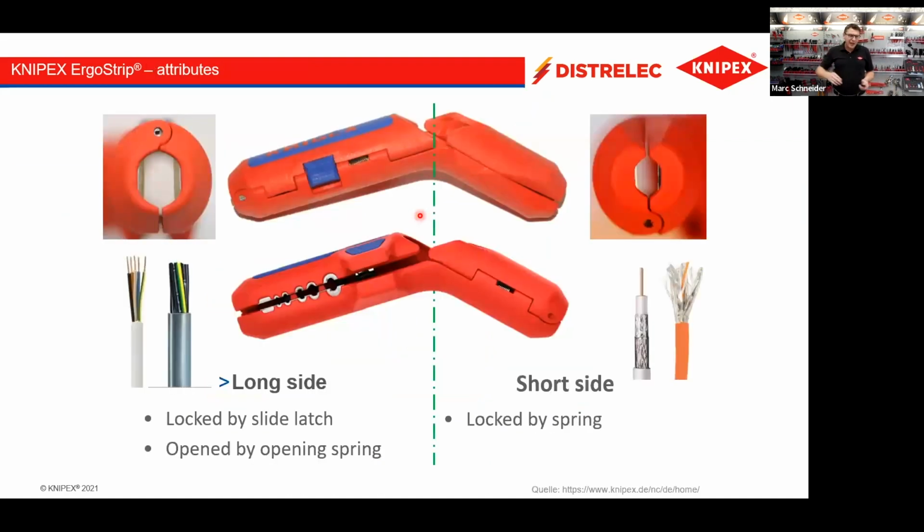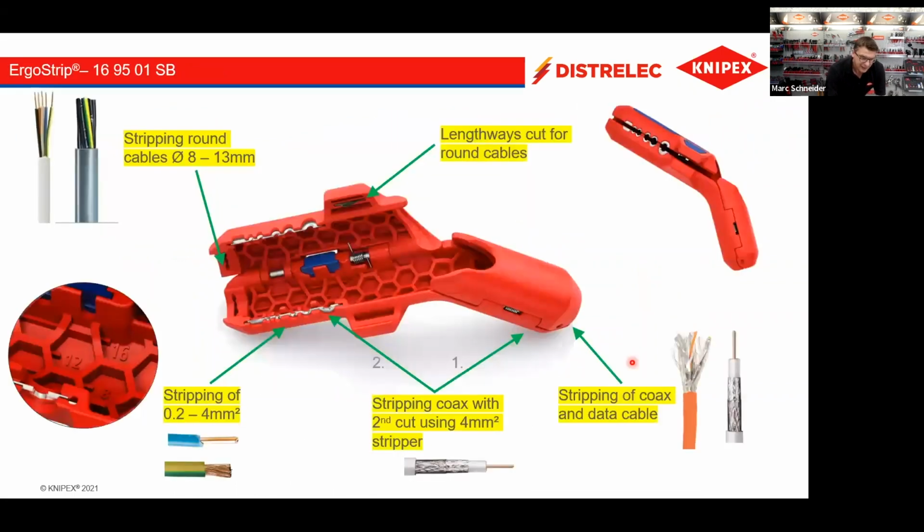For which type of cables is the Ergo Strip? The long side has blades adapted for normal building cables or for round cables, no matter if they have a rubber insulation or PVC insulation. And the shorter side has blades for thinner outside insulations, for example, for coaxial cable or for data cable. So again, you can strip round cables, only round cables, from 8 to 30 millimeter.